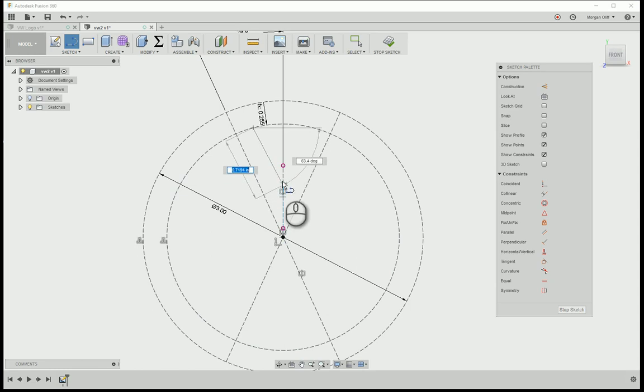It's trying to pop coincident to something that I don't want it to there, so I'll just let it be wild, and then we'll constrain it parallel here, and then go ahead and give it a symmetry constraint. Go ahead and get that out of the way.